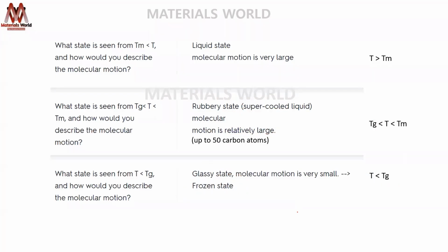Now, whether the rubbery state or glass transition region is molecular weight dependent or not is one question we have to understand. Another is, in a glassy, rubbery or any state, how will deformation behave? Once you deform your polymer, all the chains are aligned or oriented in a certain direction, so with time they are going to relax. How? By increasing their entropy.